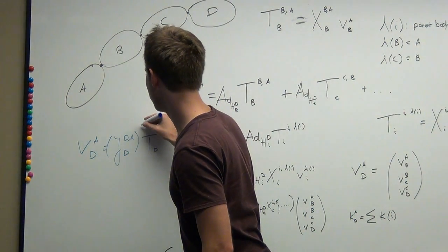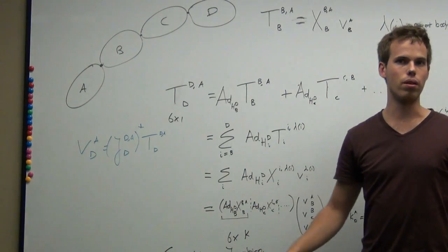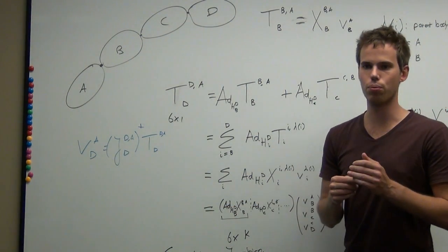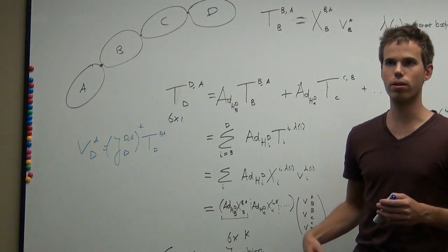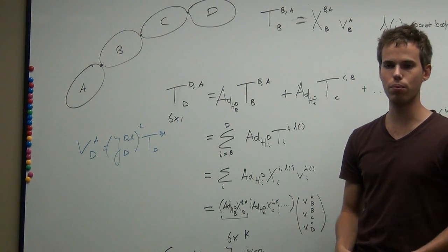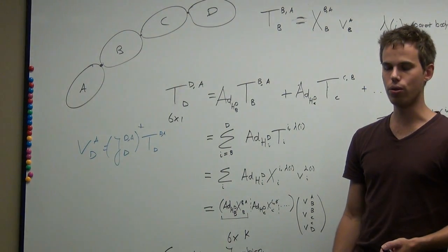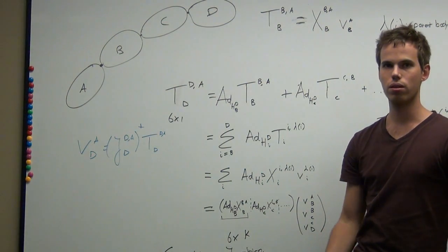Another issue is that even if this matrix is 6 by 6, you could still be in a singularity. For example, if you have a robot with a leg with 6 degrees of freedom, and your knee is stretched, then you can't achieve a velocity in this direction instantaneously.